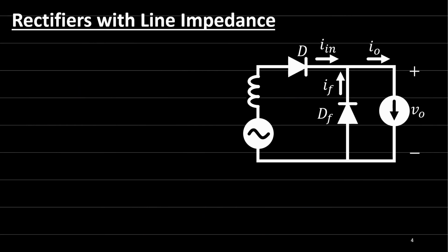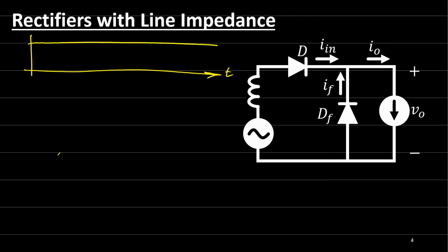Let's draw the waveforms again for the input voltage, output voltage, and the output current, and the current in each diode. And as we said in power electronics, the driving force here is the load. As you can see here, we have an inductive load. So I'll draw the current first for the inductive load. It's a constant value, I out capital, the load current.